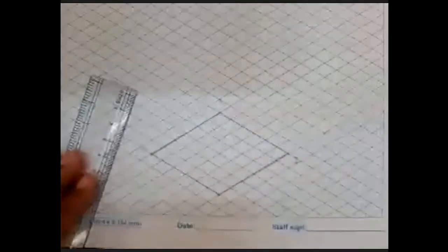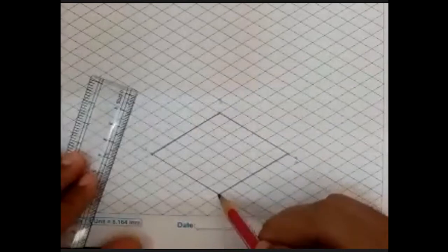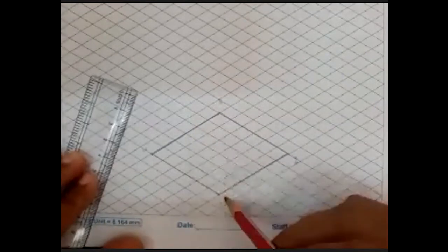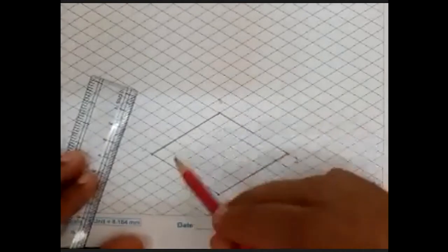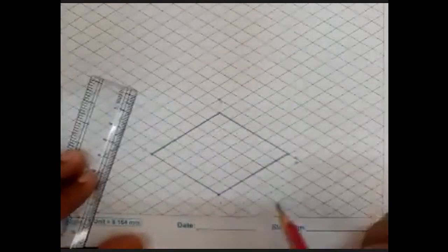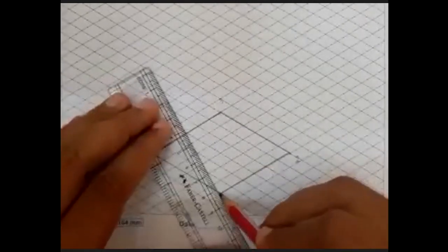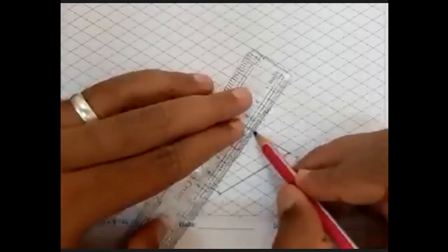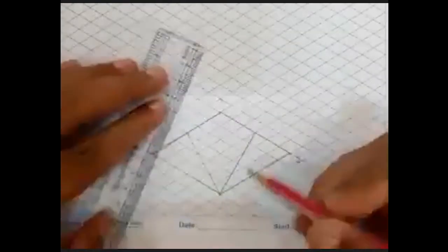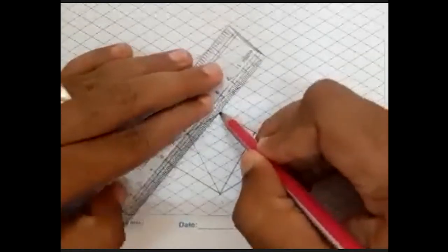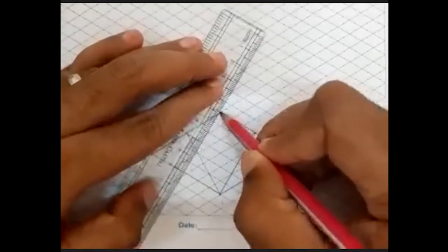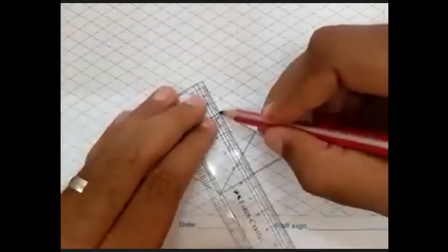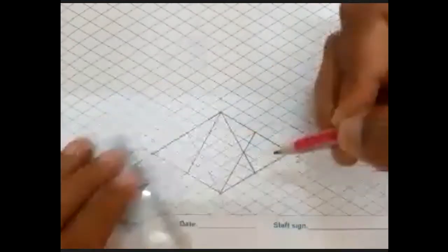Okay. Once I'm done with this, now I'm going to draw a circle, which looks like an ellipse here in the isometric projection. For this, from this corner, I'm going to join the midpoint. From this corner, I'm going to join the midpoint. From the opposite corner, I'm going to join the midpoint here, as well as to the opposite edge here.